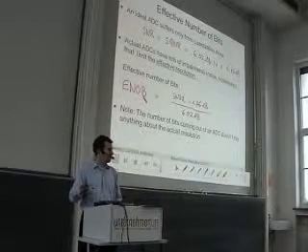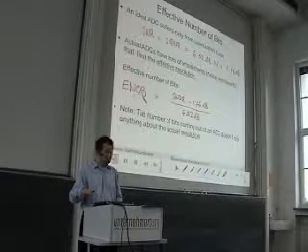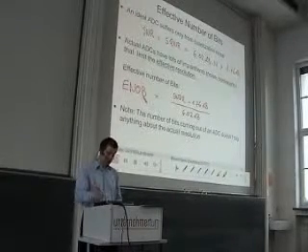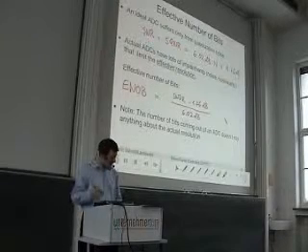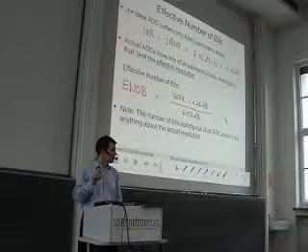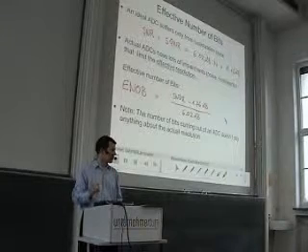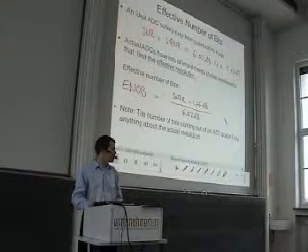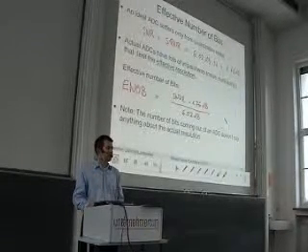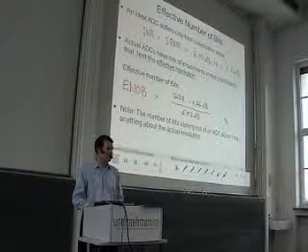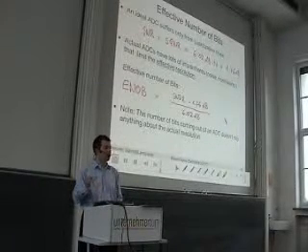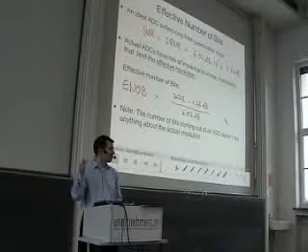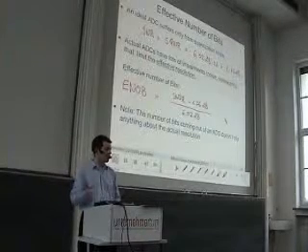So the signal to noise ratio and the effective number of bits calculated according to this formula, this is the real resolution that tells you how good your ADC can resolve the input signal. And this is the value you have to look at if you look at conference papers, if you look at data sheets.